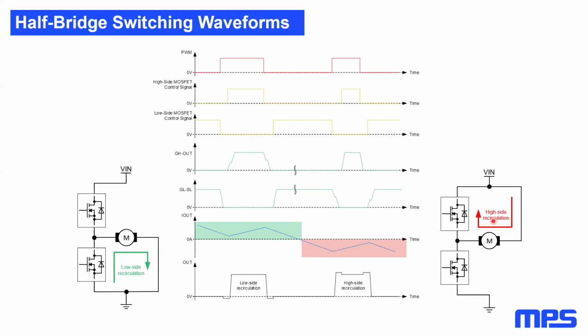The basic operating mode of a half-bridge is fairly simple. The top side MOSFET is turned on, and the left lead of the motor is connected to the power supply, while the right lead is connected to ground. Current starts flowing through the motor, which energizes it, and let's say it turns in forward direction, and the motor shaft starts spinning. A constant frequency PWM signal can be used to modulate the speed of the motor by adapting the ratio between on and off time.